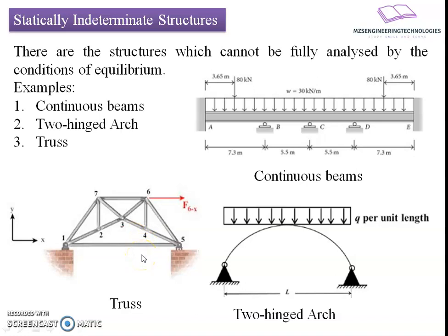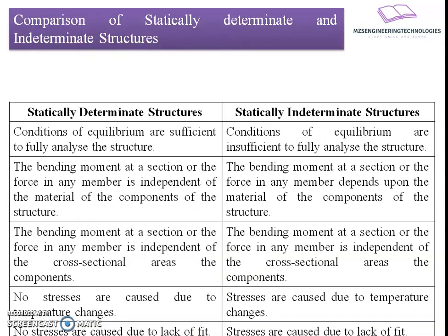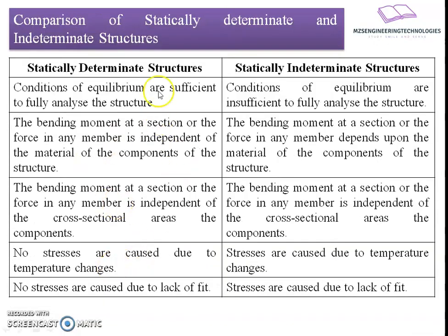Now, before going towards the analysis, let's have a comparison between statically determinate and statically indeterminate structures. The tabular format shows some key points of comparison. The very first point says that the conditions of equilibrium are sufficient to fully analyze the structure. Vice versa, in the case of statically indeterminate structures, the conditions of equilibrium are not able to fully analyze the structure and find the unknown forces.